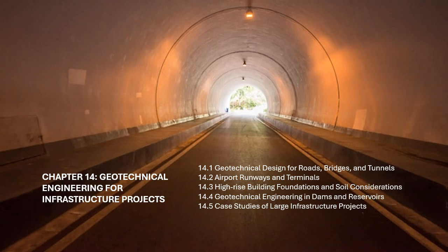Pavement design and layering. Runway pavements are typically designed in multiple layers, including surface layers, base layers, and subbase layers, with each layer serving a specific function to distribute the loads. The surface layer often consists of asphalt or concrete, while the base and subbase layers are typically made from granular materials. The thickness and composition of these layers depend on the soil conditions, aircraft loads, and environmental factors.